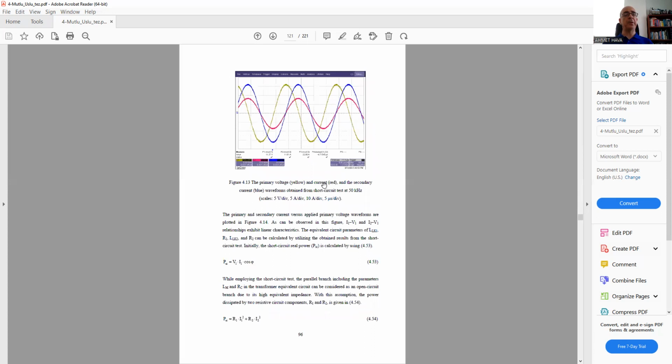When you have experimentation in the system and you want to put the graphics, there are two ways. One is you can transfer the graphic as a graphics format from an oscilloscope or from a computer screen, and then you just paste that image as is. If you take a photograph of it from a distance, then you should adjust the light and the angle of the oscilloscope screen and make sure you have enough light and you have it from a proper angle so things are visible. But no matter what you do, when you take these photographs, the graphic itself may have limitations.